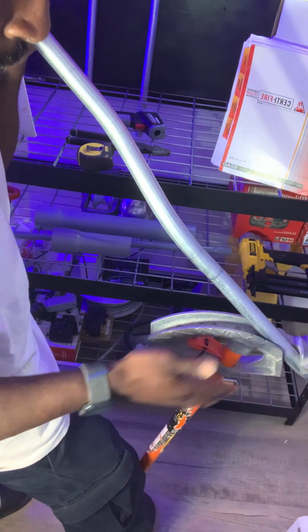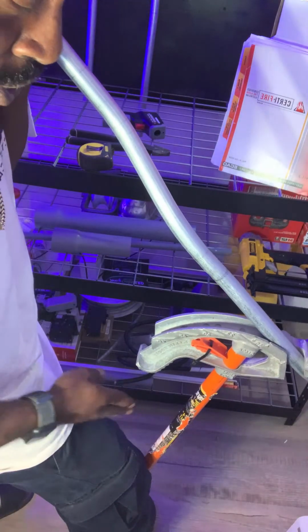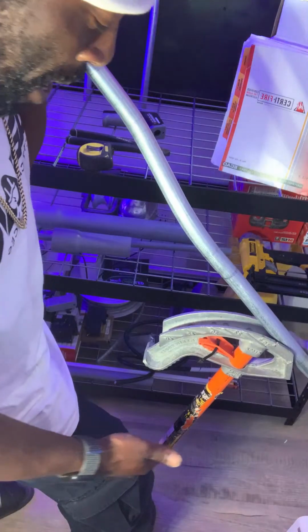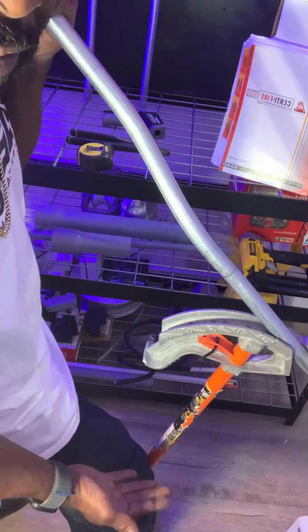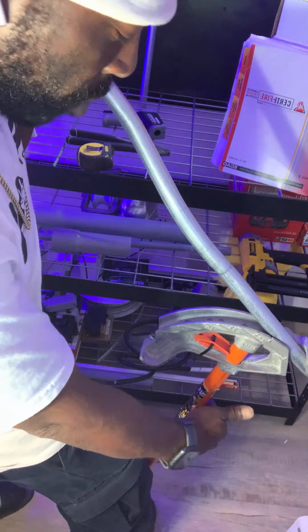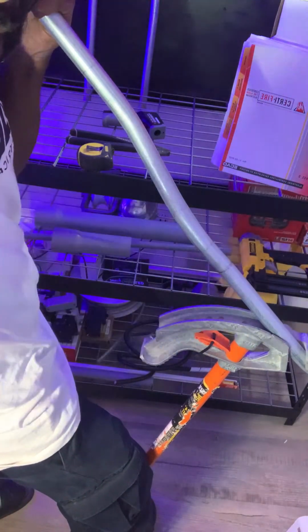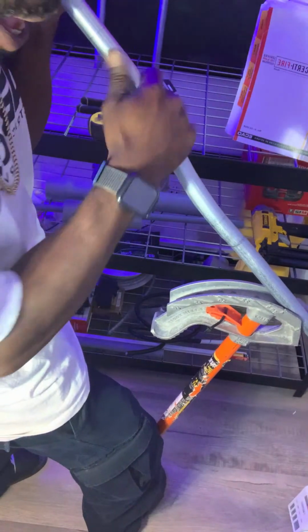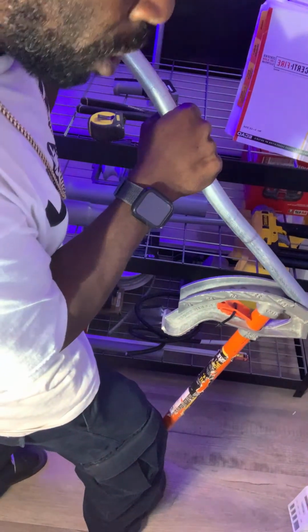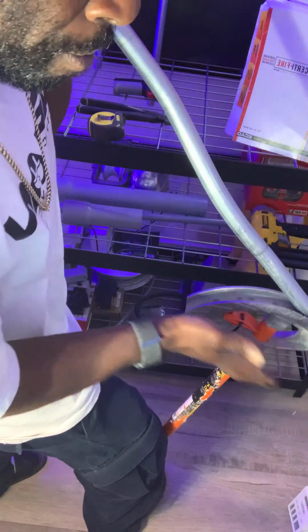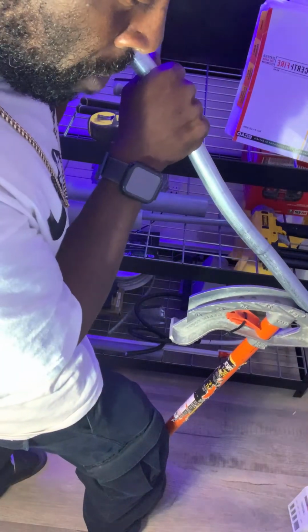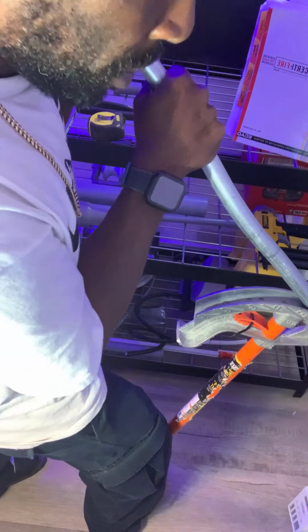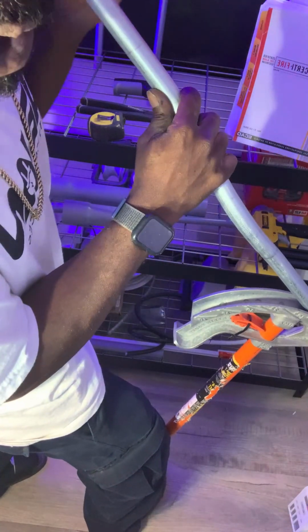My bender is going to be sitting like this. My leg is going to rest against the actual bender. My heel or my feet is going to go around the actual bender in front. As you can see, that's how I go about doing it, and I will have full control of this bender. So by me being able to lock this bender in place, this bender is not going to go anywhere.